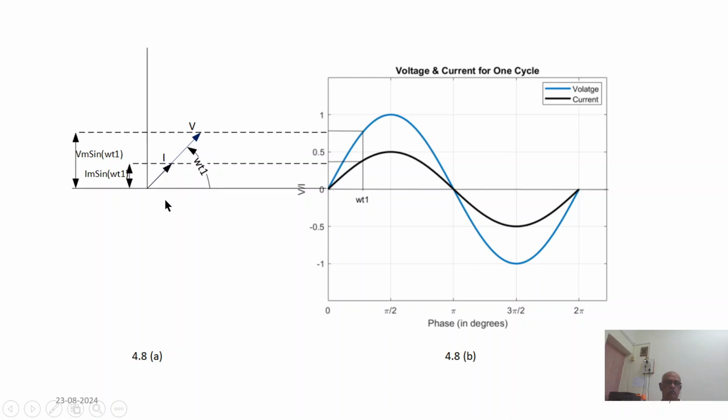So using the graphical symbols over here, we can plot the relationship between, for example, voltage and current. They are co-phasors. At every moment of time, it has got a different value, but as t progresses, the voltage and current, being in the same phase, keep changing together. So the current attains a maximum when the voltage is maximum. The current is zero when the voltage is zero.